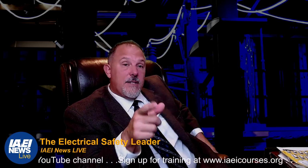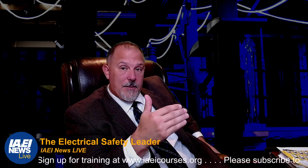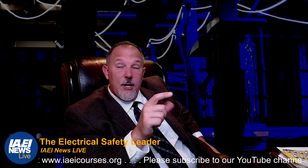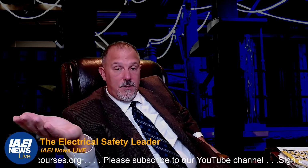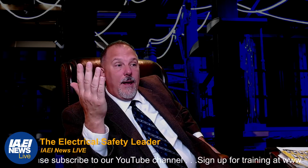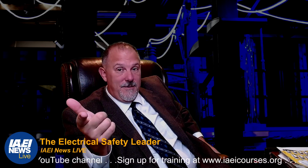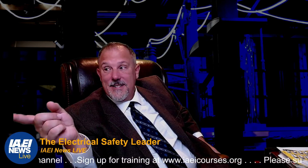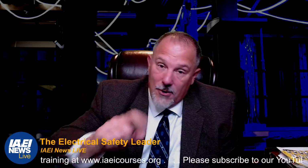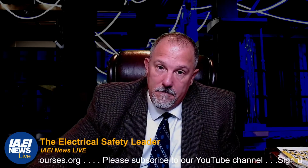Remember, the downstream device has the lower interrupting rating. The upstream device has the higher interrupting rating, and they're both going to operate and function together to clear the fault. So you do a series rated system, and you have motor contribution. You didn't consider 240.86(C). That's your code reference. And now you have to fix the problem.